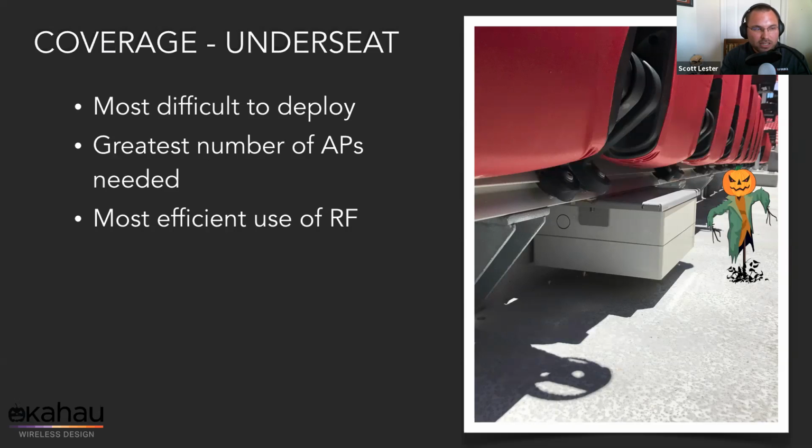But from an underseat perspective, we have the benefit of our RF essentially spewing out into space. So rather than having destructive interference from an overhead or a handrail deployment where we're shooting signals at each other, with our underseat model, for the most part, we're going to direct that signal out into space. So we have a much better chance of potentially using a channel multiple times, depending on the size of the venue. There's a lot of things that go into that. Reuse, if you will.